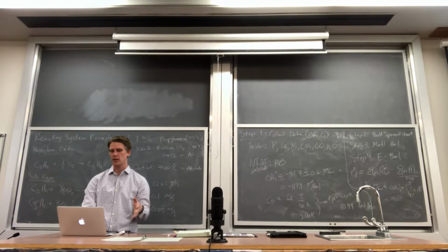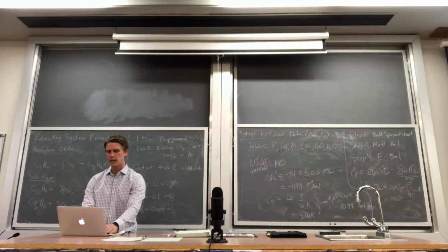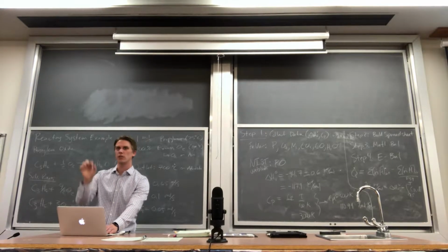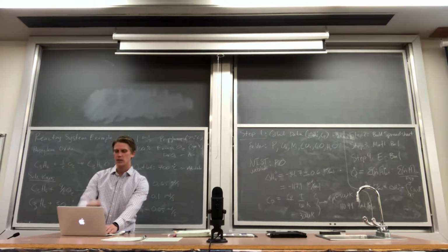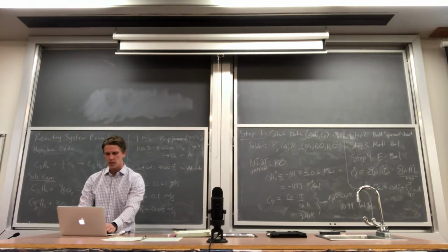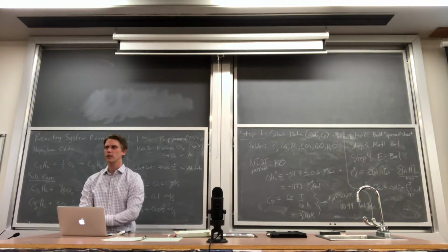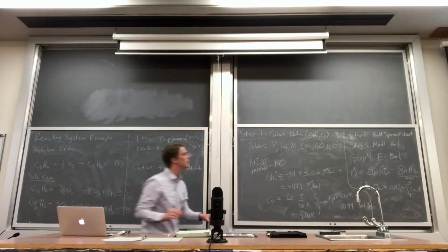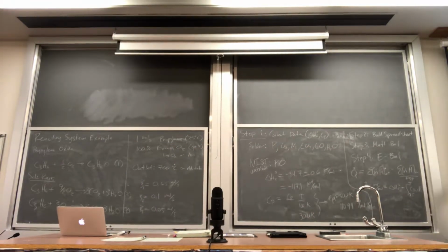And same thing on the back end here, of course, right? Mole fraction, pretty straightforward to calculate. And I also add in these double check consistencies. If that doesn't add up to 1, then I've screwed something up. Sometimes when you add a row or subtract a row, maybe your equation won't capture that new one. But so when you add in these double check consistencies, then you have another way to verify that things are going well. Enthalpy final is the same equation, right? But the difference here is that I'm pulling it all away from one single final temperature cell value, as opposed to on the inlet. Here I have individual temperature flow rates in, but the outlet I'm just saying it's one combined flow rate out.